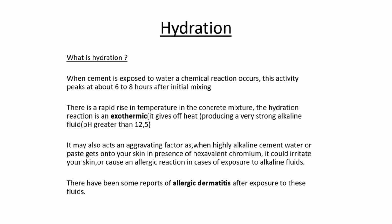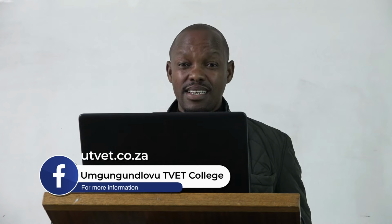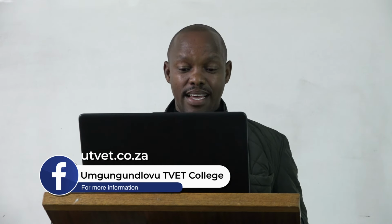It may also act as an aggravating factor, as when high alkaline cement, water, or paste gets onto your skin in the presence of hexavalent chromium, it could irritate your skin or cause an allergic reaction. There have been some reports of allergic dermatitis after exposure to the fluids, which means when you're touching cement, your hands can get the allergy, and your skin will end up peeling off because of the cement.